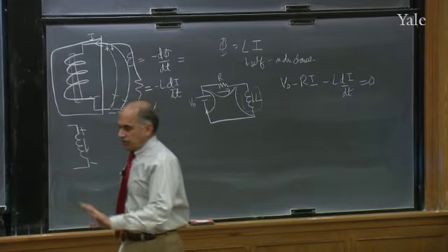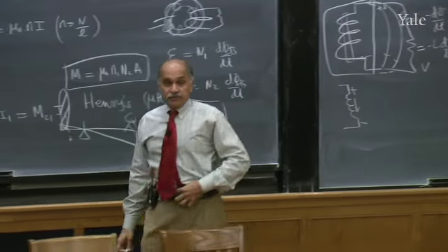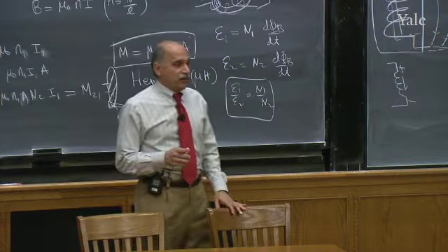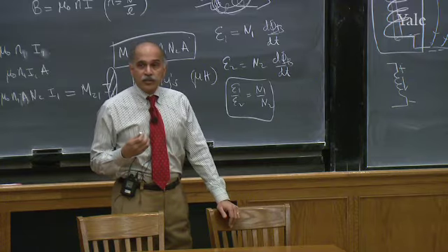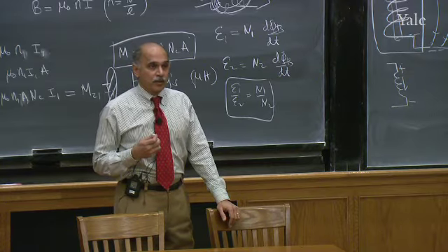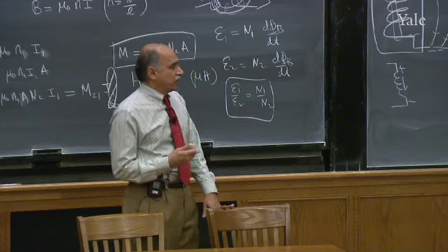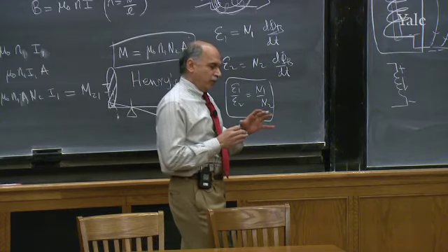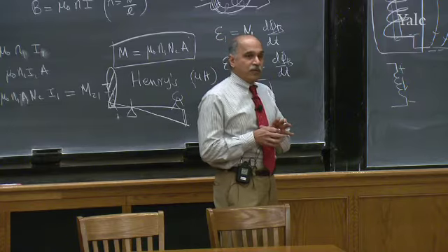So here's a one-word summary for those of you who have heard enough. We learned the notion of voltage, or a potential, can be defined only in a conservative problem. But a changing magnetic field in an inductor definitely is producing a field which is not conservative. So if you go deep into the coil, you will have problems defining voltage.